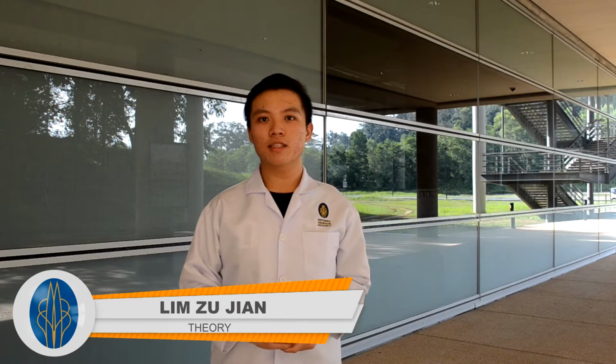At the beginning of the batch sedimentation process, the solids are uniformly distributed in the liquid column. After a short while, the solids have settled and give a clear liquid region, which is zone A, and zone D for settled solids. Layers A, B, C, D are formed as the settling process continues, and the depth of